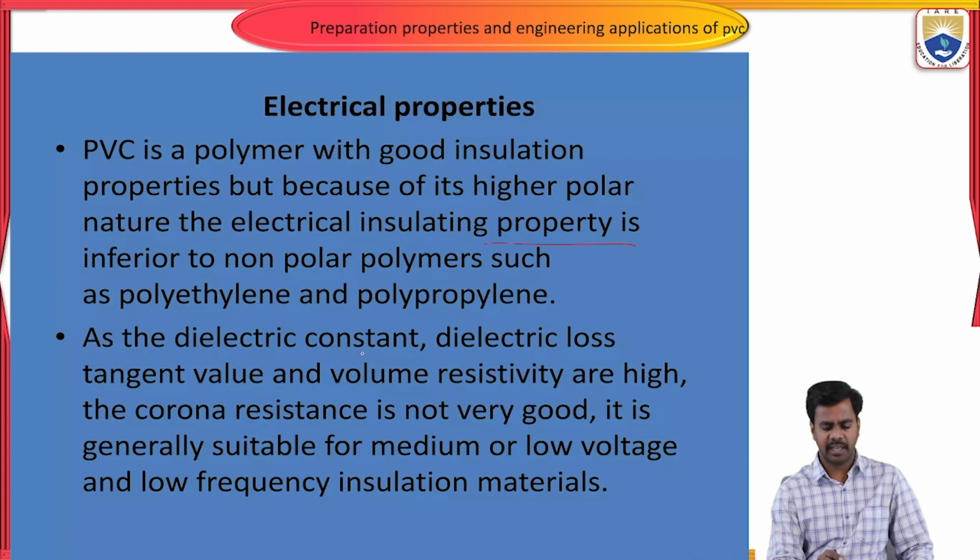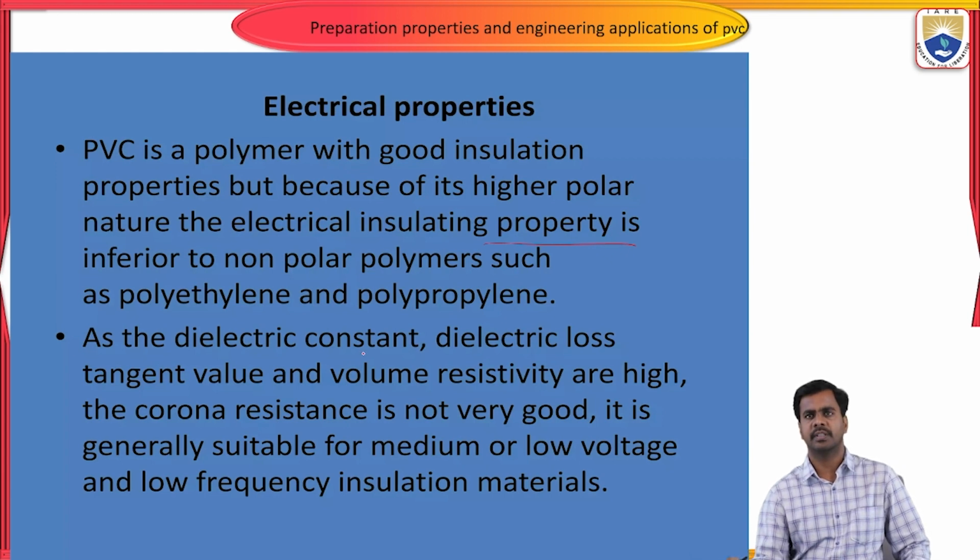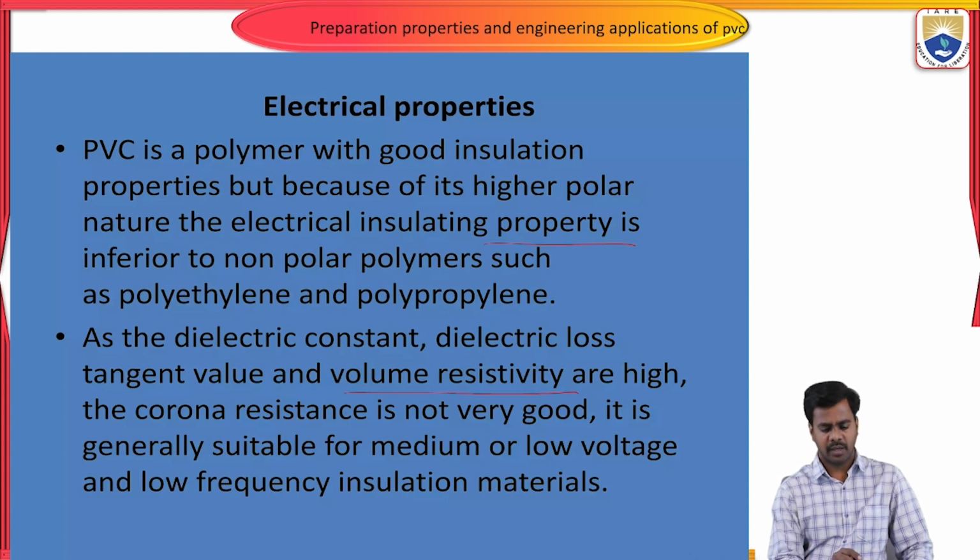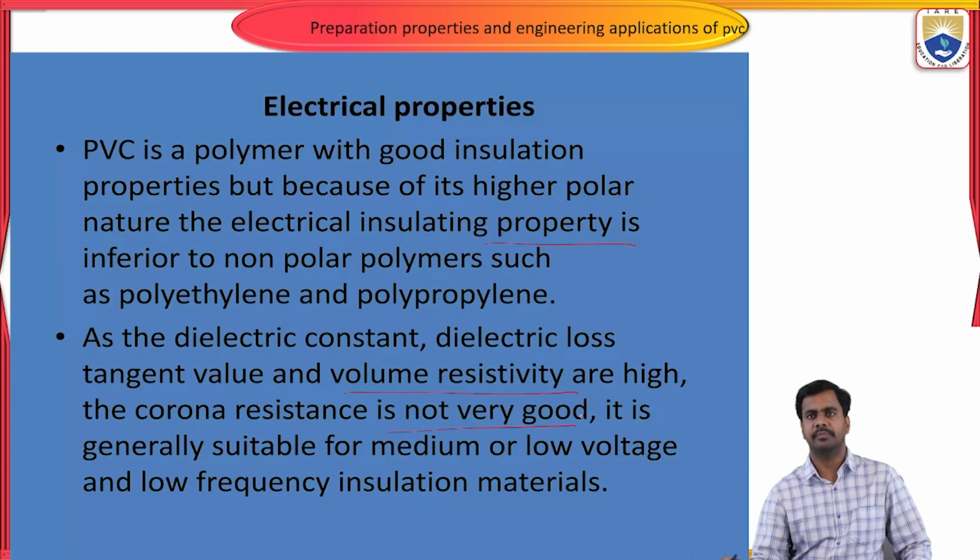The dielectric constant, dielectric loss tangent value, and volume resistivity are high. The corona resistance is not very good. So it is generally suitable for medium or low voltage and low frequency insulation materials.